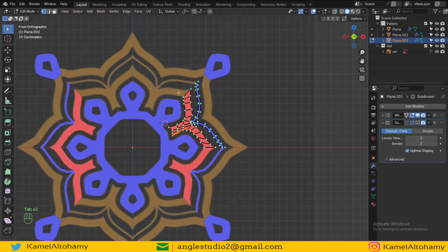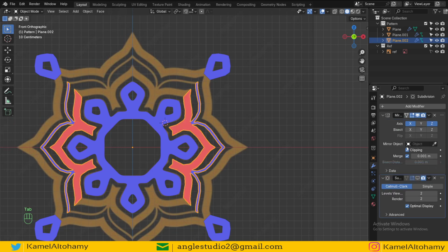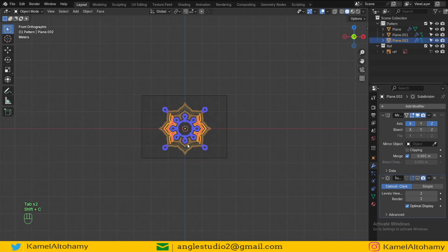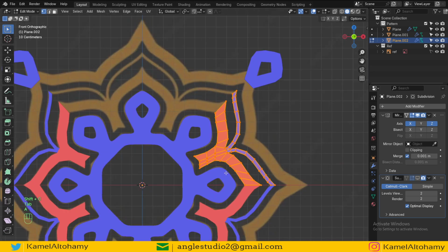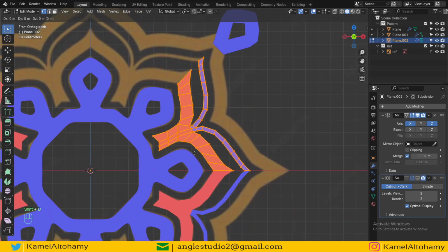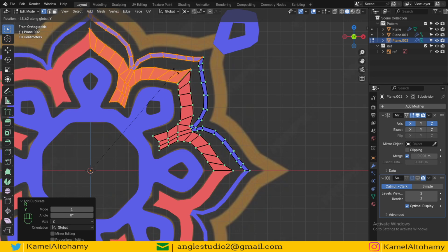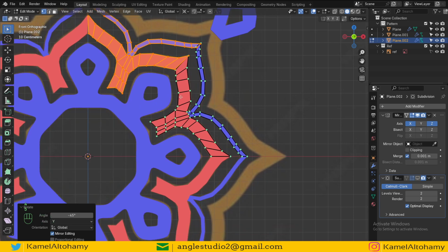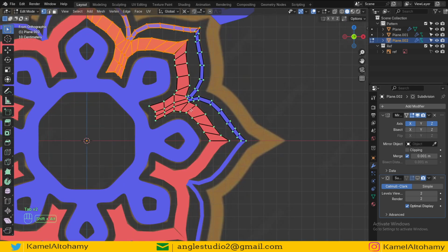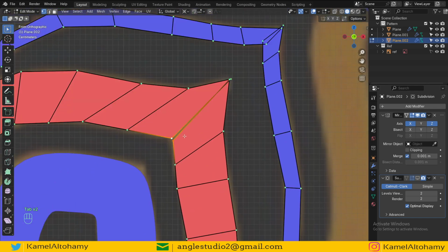You can rotate. It's 30. It's a complete circle, so you can disable the clipping and make sure that the cursor is the center, and press Shift D, then Y, based on the cursor, of course. And 45, of course, is fine for now. And after that, let's merge these. All these bonds will be merged at the center.